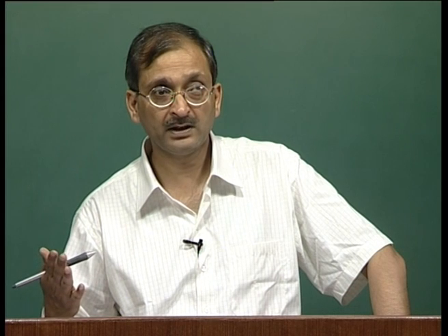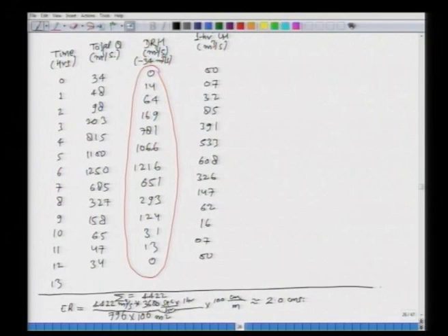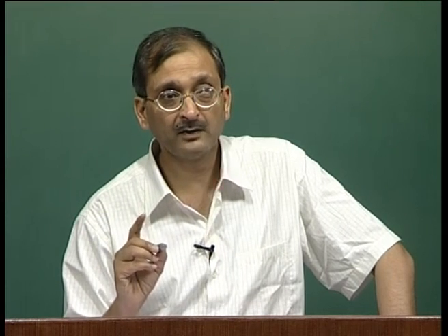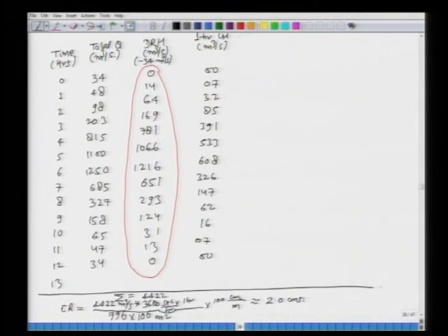What we have to do is, now we have to develop n columns. What is the value of n here? N is equal to 2, because from 1 hour we have to find out 2 hour unit hydrograph. So, we have to develop 2 columns and one of them is this one. So, we need to develop one more column which will be lagged by d hours. And what is d? D is 1 hour here, which is the duration of the effective rainfall. So, you have lagged d hour UH, this is also in meter cube per second. When you lag it, you can just put a dash at the initial one and then just copy this whole column, you just shift it. So, this is called lagging.